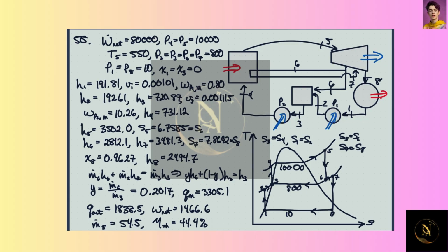In this problem, we have a steam power plant again, the reheat regenerative Rankine cycle. Let's see here. It's best to probably just walk through the schematic. I drew both turbines as one. You could either say that this is a high pressure turbine and then there's a low pressure one afterwards, connected by the same shaft. But I just drew them as one, and just assumed that we kind of had a bleed.